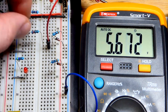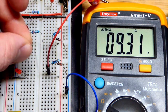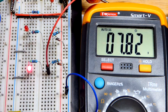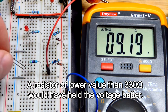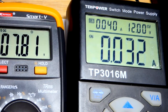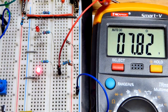So I'm going to yank that LED, and we got this other one down here. Again, this one's set to 9 volts right there. Again, 330 ohm resistor, which isn't having to pass near as much current. So there you can see, this is a 470 ohm resistor since we're protecting an LED from 9 volts. And there you can see we got 7.82 volts. And so it looks like that one pulled it down quite a bit. And so we might need a lower value resistor for the zener diode to pass this much current. We'll look at how much current's flowing, 32, and I'll remove the resistor, which is rather warm, from the 5 volt one. And there you can see the current went down. So a lot of that current was for that circuitry there.